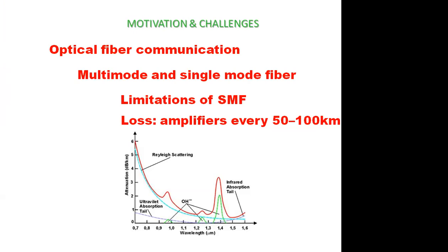Repeaters. Right. What is a repeater? What is a repeater and an amplifier? Whether both are the same or they are different? We know what an amplifier is. It increases the signal strength. So after 100 kilometers, signal strength is reducing. Use the amplifier, it increases. Now what is a repeater then? A repeater is basically a receiver, amplifier and transmitter. That means a repeater consists of an amplifier.